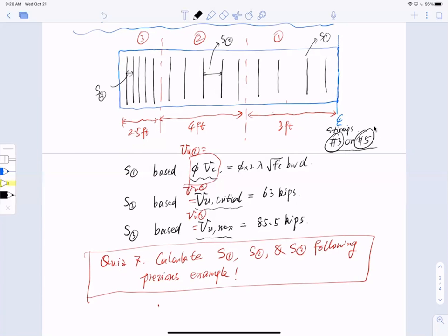My personal favorite for small beams like this is number 3. But some people like it to be stiffer, so they have larger spacings. I want to caution you a little bit because you want to make sure spacing is at least the minimum. There's a minimum, remember? If you pick number 5 a lot, you realize that sometimes you don't have to do any calculations, the lazy side of it, but you still have to make sure they exceed the required value.